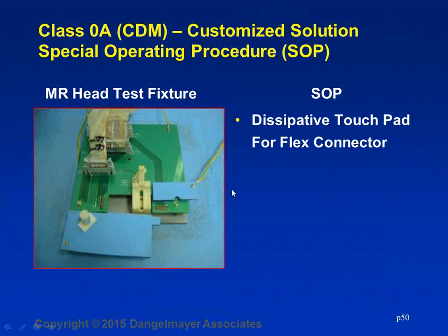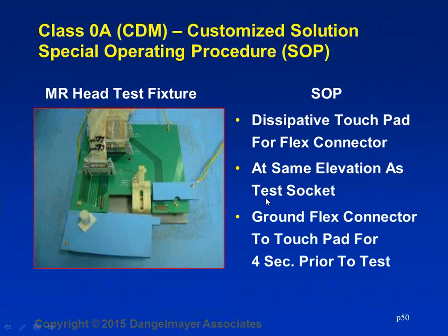What was surprising is that we had to wait 4 seconds for the charge removal. Anything less than that would enable some residual charge to remain on the device. So it required a full 4 seconds to fully remove the charge from the product before you could put it into the connector safely.